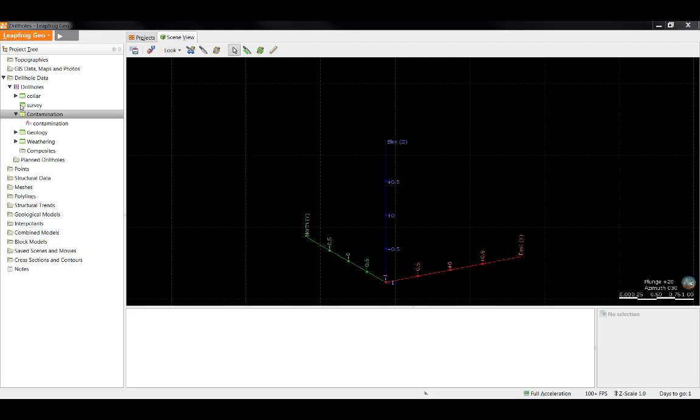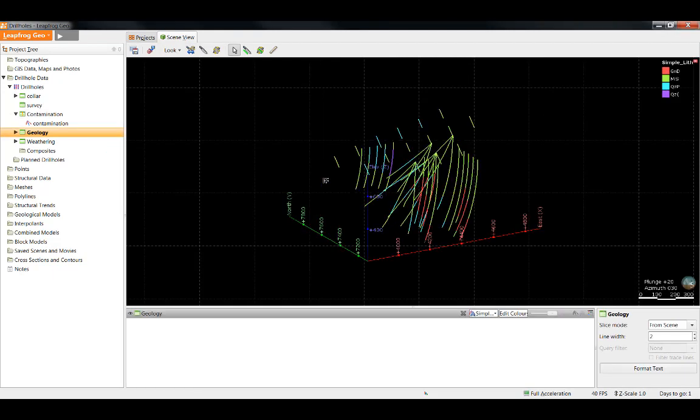There are two different color maps available in Leapfrog, discrete and continuous. Discrete color maps are used for coloring discrete data, which is data that can only take certain values. For example, geology data is always colored using a discrete color map because the values are different rock types. Discrete color maps can also be made to display grade data which has been split into bins. For example, assay data could be visualized in bins with different colors for values between 0.75 and 1, 1 to 1.25, etc. We'll see an example of that later on in this tutorial.